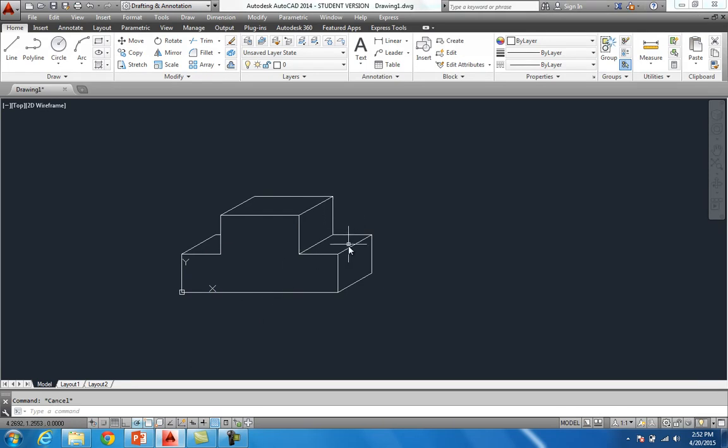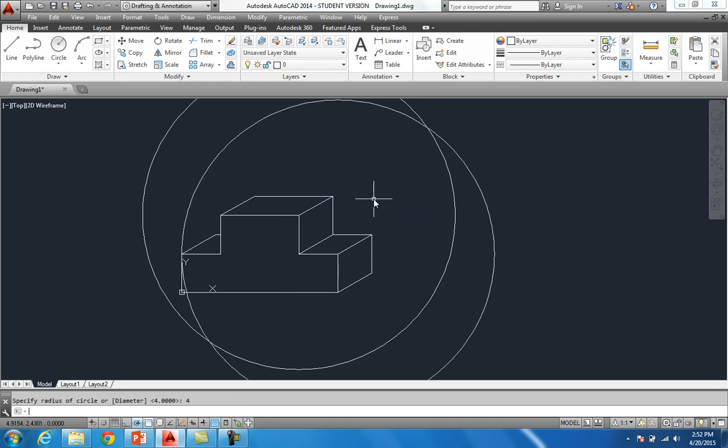Now, let's say for instance I want to make this right here a big radius that comes in here. Both of these are 1 inch over, this is 1 inch up. So all you'd have to do is come here, and let's say we want to put a 4 inch radius here. Grab your circle, go from this end point, hit your center radius, grab it right there, bring it down, and type in 4, but it should smooth right into it, as you can see there.